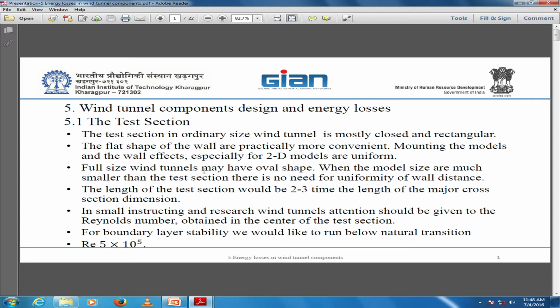In the diffuser is the worst destroyer in terms of loss. And these are the definitions of the diffuser. You have the expansion angle. We deal with the half angle. There is the entrance diameter and the exit diameter, and the area ratio, which is the ratio between the exit to the entering area.